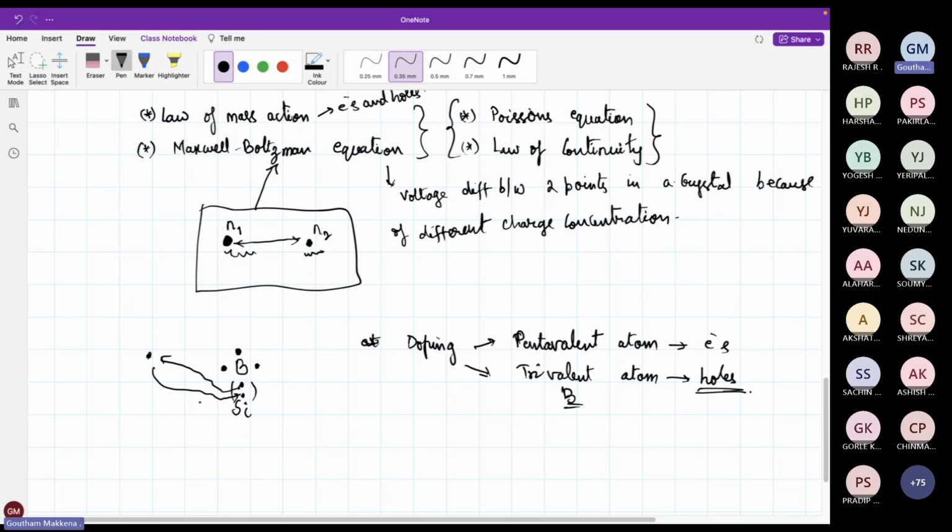It is nothing but the movement of charge visualized in a reverse fashion. That's it. Okay. So there are some open covalent bonds that are present. Your electron goes and sits there at point of time T1. At the point of time T2, it goes and occupies some other location. So this movement in effect looks like a positive charge has moved from P2 to P1. So this is nothing but considered as a hole.